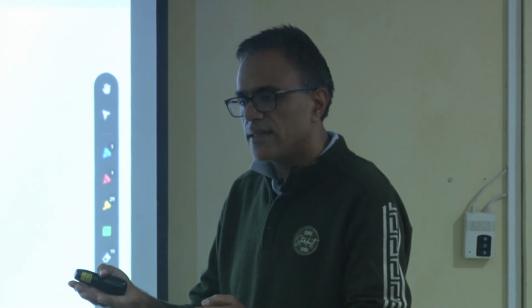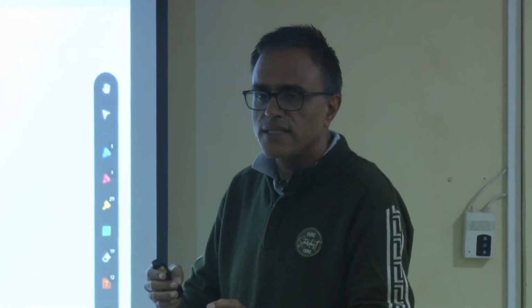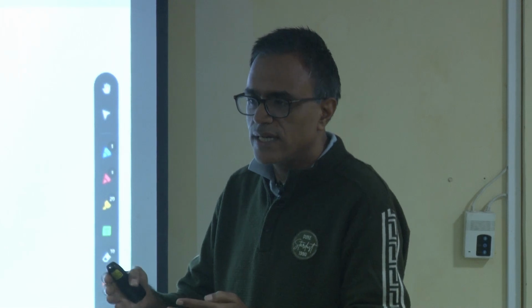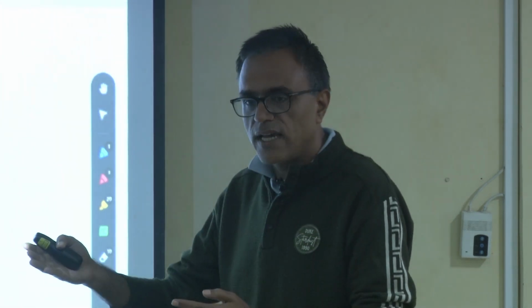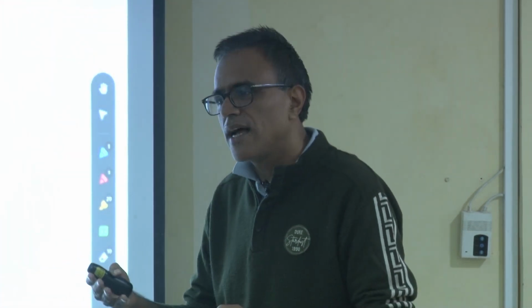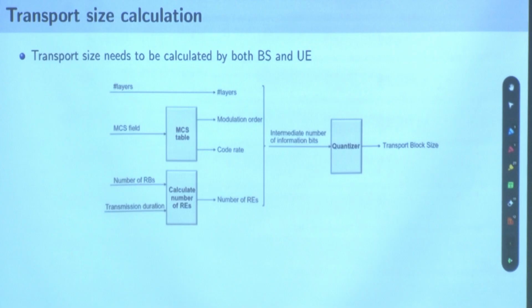And the second case is if the modulation order is larger. For the same number of resources, the transport block size will accordingly be larger, because you can transport a larger number of bits. So we'll see this explicitly when we calculate the transport block size. And it needs to be calculated by both the base station and the user.